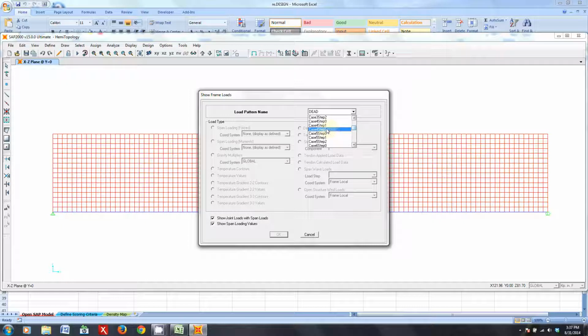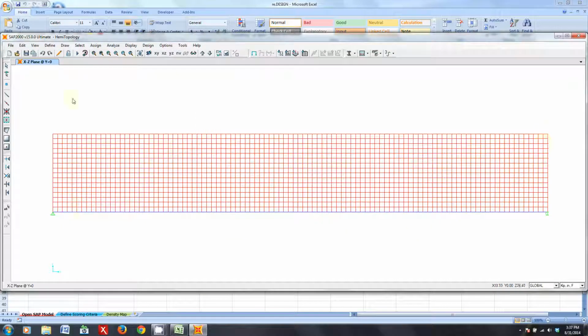And in fact, that's exactly how I got these loads on this, rather than doing it all by hand. I just assigned all the loads to these frame sections along the bottom using ProtoBridge, and then I deleted the rest of the structure except for just half of the bridge and just the decking support surface with all my loads applied to it. I put pin and roller supports at the bottom, and then I filled up pretty much the entire top part of the bridge, not with members, not with frame sections, but with area sections or shell elements.